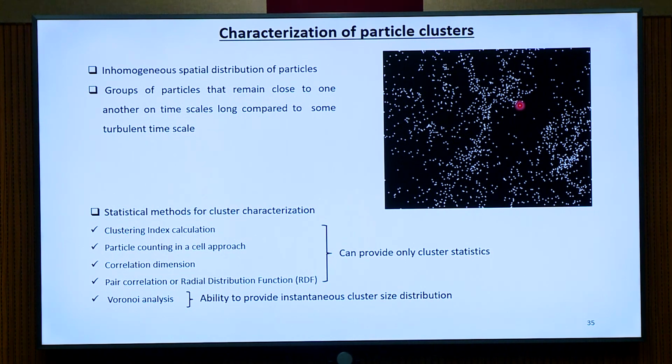Somewhere you have more droplets, somewhere there is a void. If you use PIV for this to find the velocity, it may be that in some regions of your interrogation area you have a limited number of droplets. So you don't have control over the seeding density as in the case of single phase flow. That is an important difference.